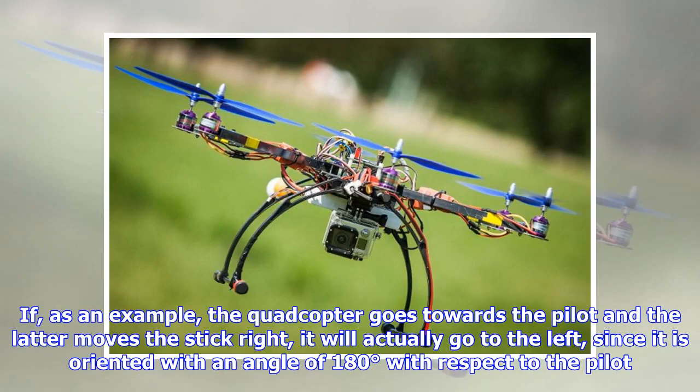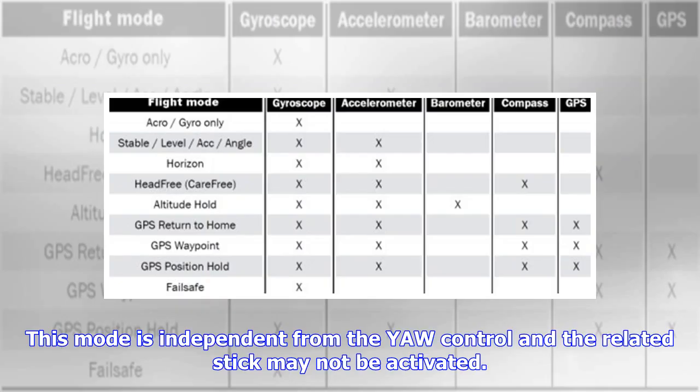If, as an example, the quadcopter goes towards the pilot and the latter moves the stick right, it will actually go to the left, since it is oriented with an angle of 180 degrees with respect to the pilot. This mode is independent from the yaw control and the related stick may not be activated.